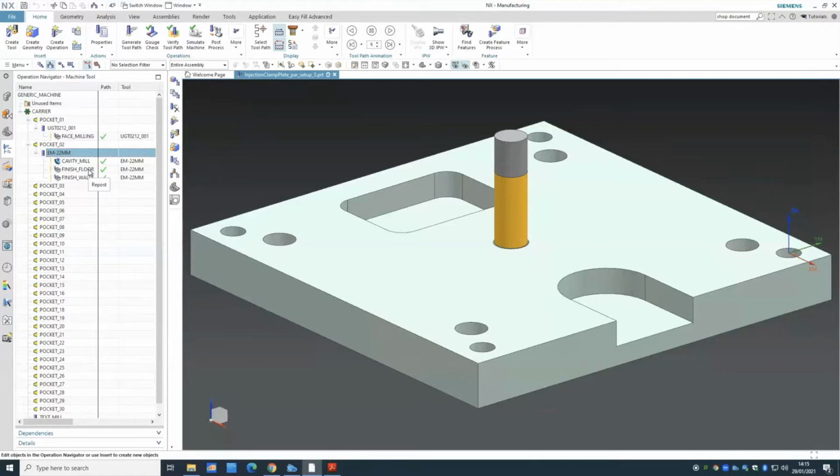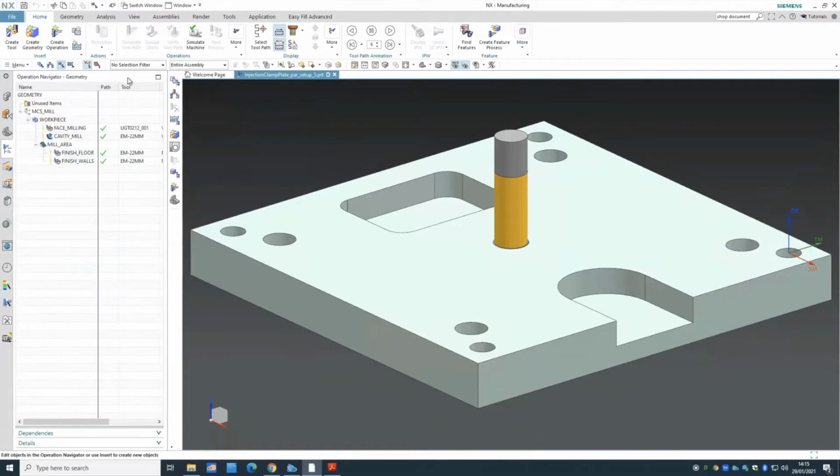For every single process, if you remember, there was a sequence of doing that within the CAM. First of all, you have to make sure that you have a correct setup. I received a couple of emails from your colleagues saying they had issues, and I really recommend coming back to those videos, because having a correct setup is really important. Otherwise, the software won't be able to continue. So defining the coordinate systems, the workpiece, and the bounding block is really important. And also if you have a sub